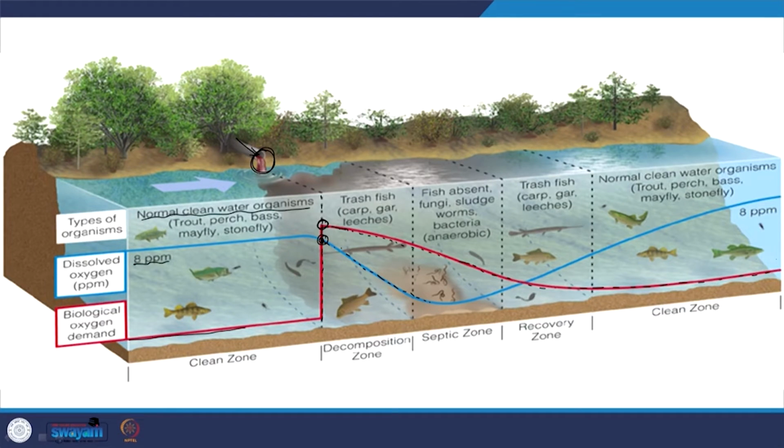We looked at this graph earlier, or even here, dL/dθ is equal to minus kL, let us say. So, L at θ is equal to L0 e^(−kθ). You see exponential decay, that is what you see out here. But with respect to DO, what is going to happen? Obviously, it is going to decrease because organic content consumption, or aerobic degradation, takes place.